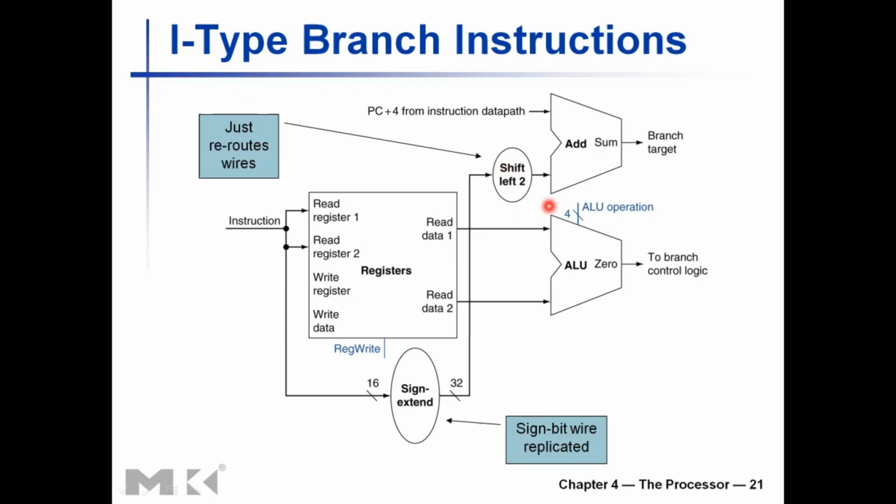Say, now if I try to draw this, you get a 32-bit signal here, right? If we take the least significant signals out of that, that is wire 0, this is wire 1, and this is wire 2, wire 3, and so on, and you have 32 wires like that, right? So that is coming from the sign extender. Before giving it into the adder at the top of this figure, you need to add 2 zeros here, right?